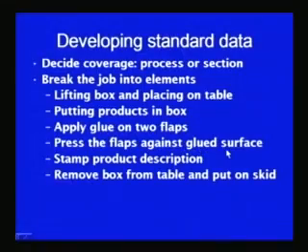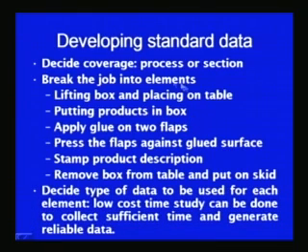Say one operation of packing and pasting the label on the box is broken down into these 5-6 elements, then time values for each element are obtained, and later on can be used to find out the time required for performing a similar kind of operation on another packing operation, which may require different types of items to be packed, or different sizes of flaps to be pasted on the boxes, and stamps to be put on.